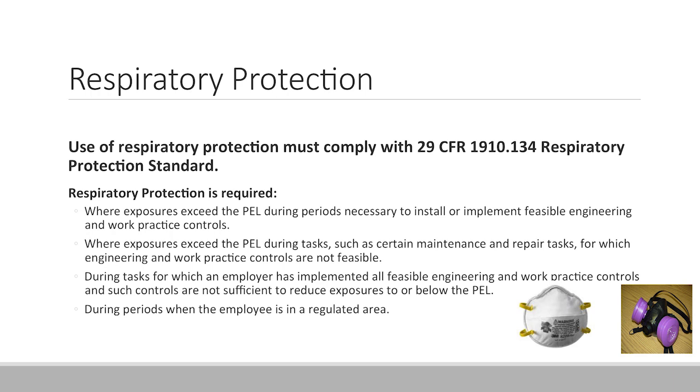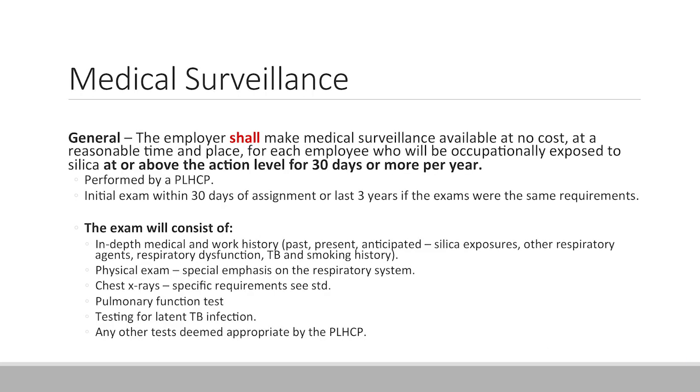Before wearing a respirator, employees must have a medical evaluation and a fit test. Medical surveillance: if an employee is required to wear a respirator 30 days or more per year, a physical is required by a licensed healthcare professional.